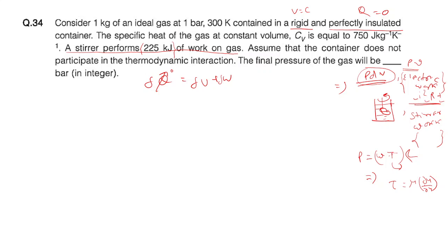Yes, sir. Shear stress multiplied with the area. If it is constant, then multiply with area. Otherwise, if it is a function of radius, then integrate. Correct? Yes, sir. Maybe many of you did not get it, but if not getting, let me know.